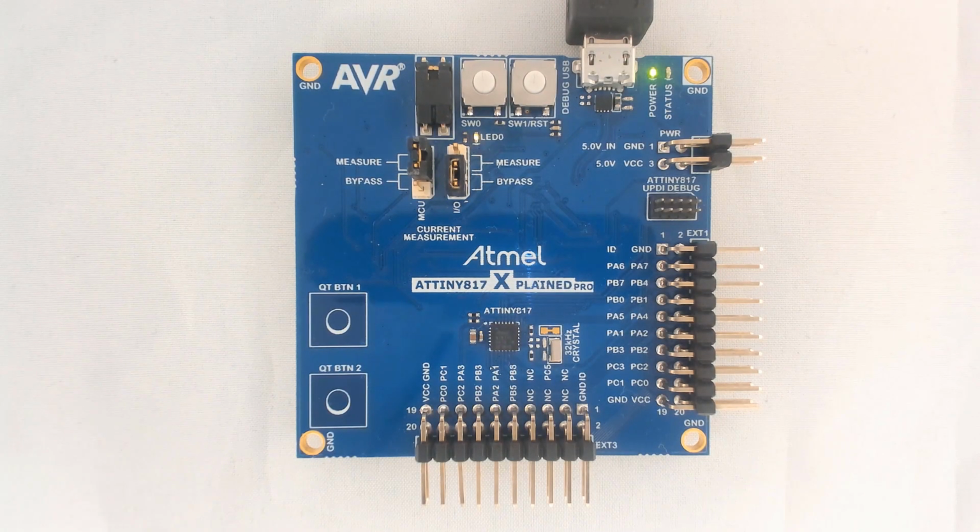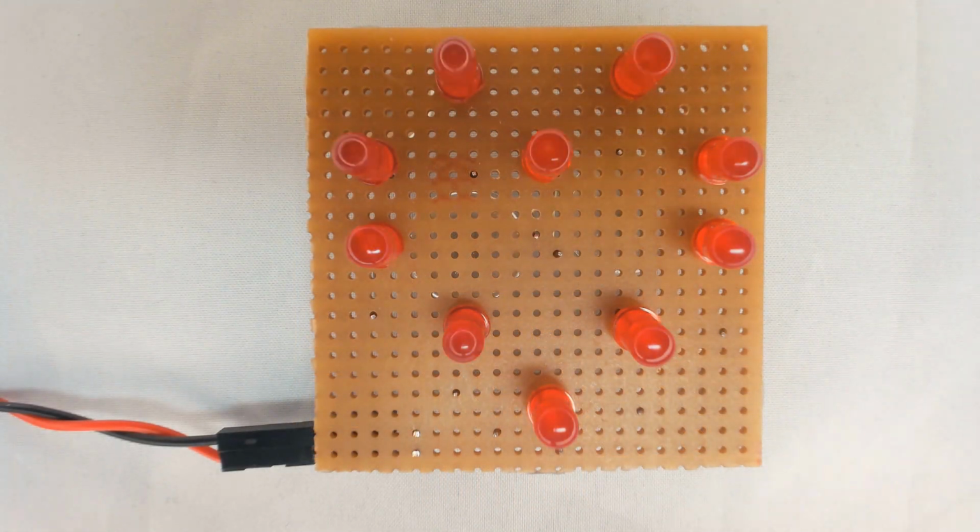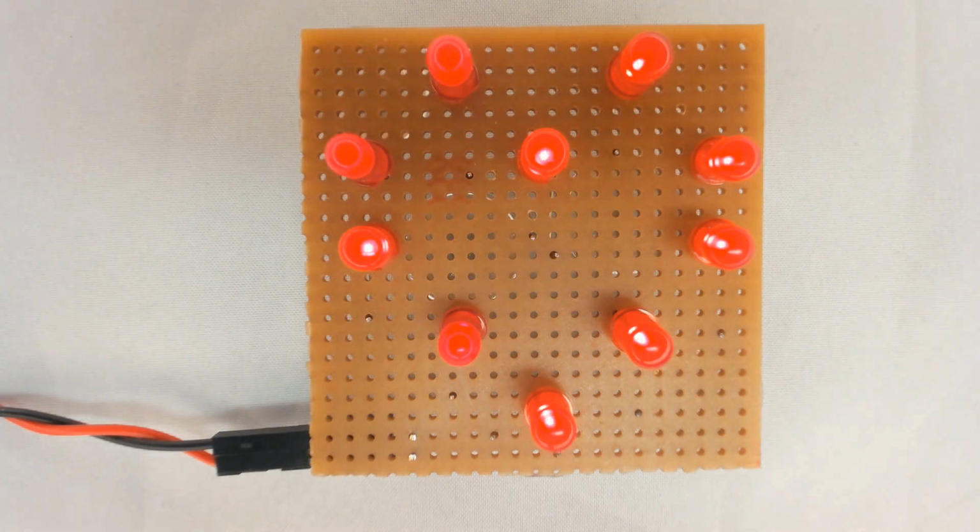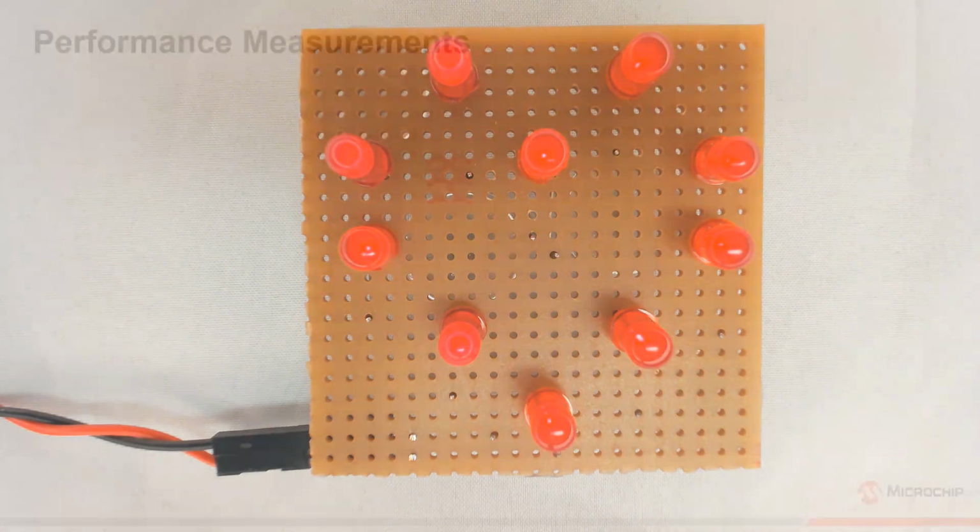Now we have created an application where an output pin will produce a PWM signal with a varying duty cycle that makes the LED pulsate in a heartbeat-like fashion 100% free of the CPU. By connecting my custom LED array to the same output pin, the effect is made a bit more exciting. From here we can also create a function to change the beats per minute and/or pulse width of the heartbeat during runtime. Now let's take a look at some performance measurements.